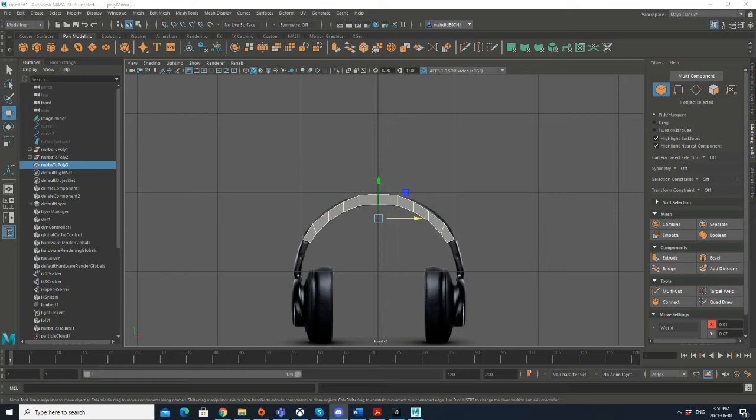Yeah, as I said, sorry, it's possible that Maya just decides not to help you at all. So what you can do is to select a few of the edges at each step. For example, select 4 edges and then select 4 edges from the down piece, and then select bridge between them.